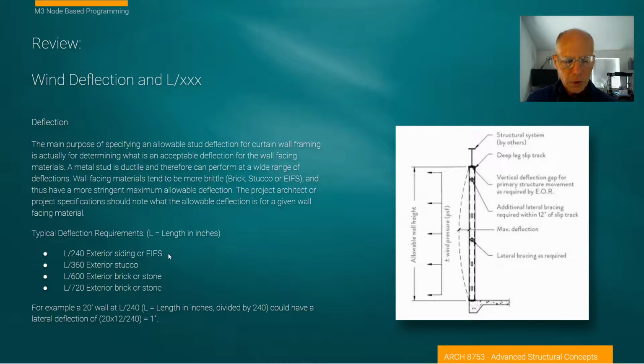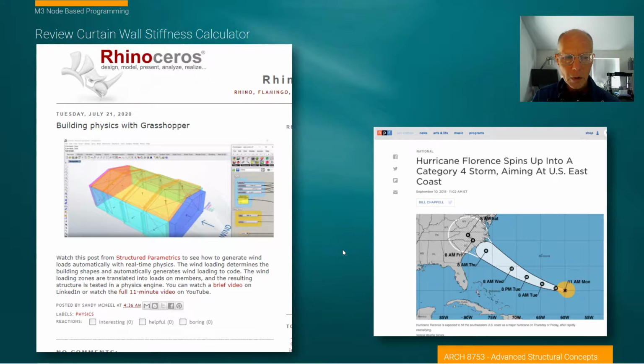The reason for this is just to give us a handle on this L value. Obviously on lightweight flexible surfaces, we allow more deflection. On brittle surfaces, we allow less deflection. They don't really do glass framing, so I'm sure there are manufacturing specifications for that also. But this is hyperlinked, and you can go to that.